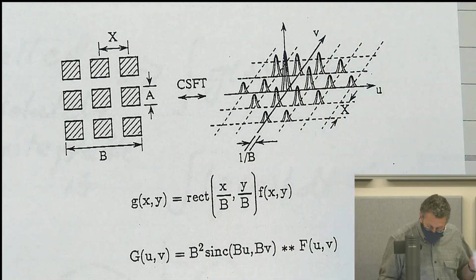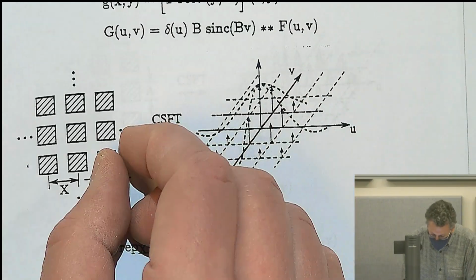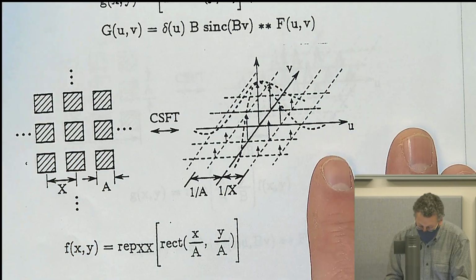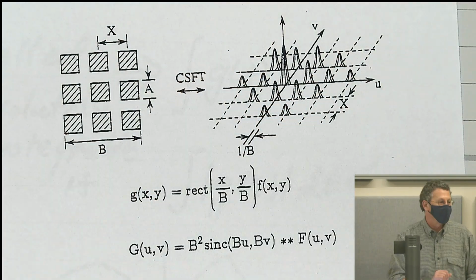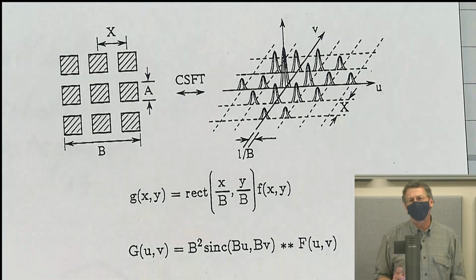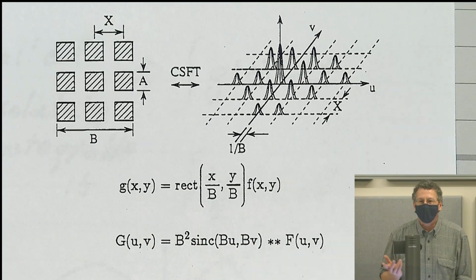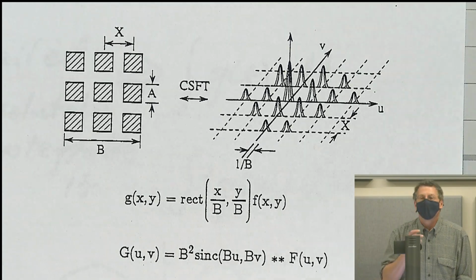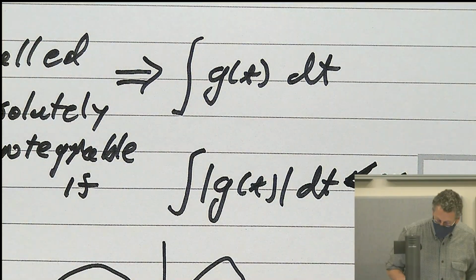So it's actually 2 sincs here. There's a big envelope of the sinc associated with the size of the small thing, and then there's the little sinc corresponding to the big window, right? It's easy to get confused on this stuff, even when you've done it for a long time. The best way to sort things out is to keep in mind that anything that's big in space is small in frequency, okay?